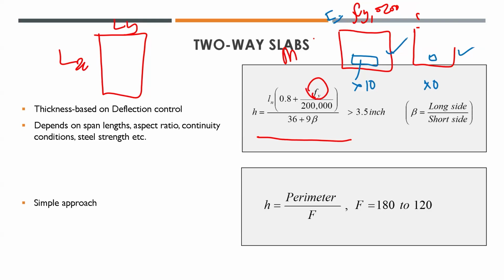You remember moment curvature, right? You can use moment curvature to calculate stiffness. So SAFE can do that. It can go back and calculate the moment curvature of the slab and then use that moment curvature to calculate the stiffness and calculate the more reliable deflection, including the long-term effects. So it's a longer procedure.